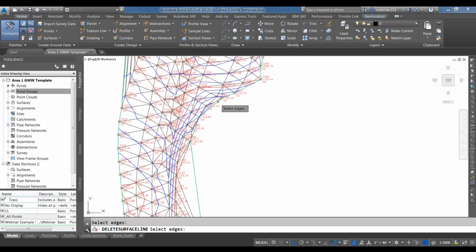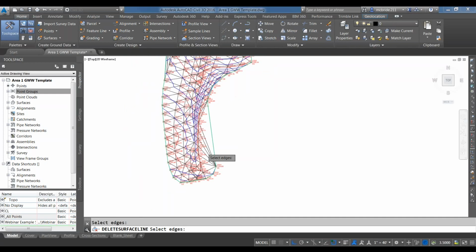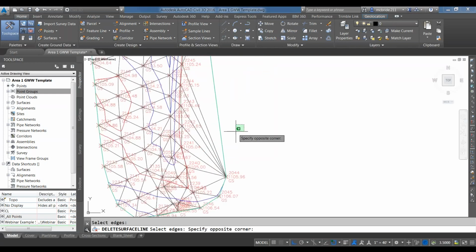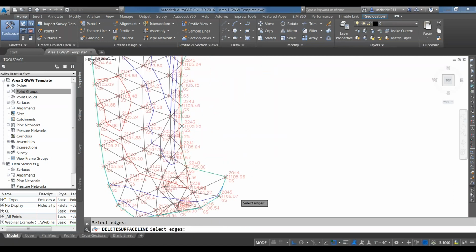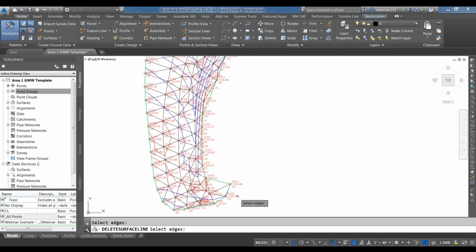Okay, there you can see it just drew the boundary closer to where the survey points are actually located. And I'm going to do that at several spots. So I'm going to click out here and draw down to the left over to where I want to stop, to make sure I have those lines selected, and then right-click. Okay, so I just took care of that little area.